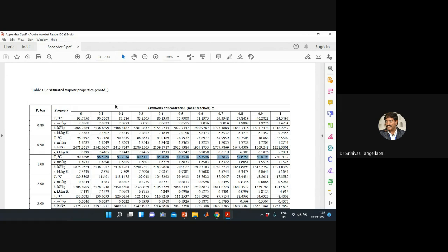Okay, now I covered the extreme ends, the fully liquid properties and the fully vapor properties. Now the question is: if the state is between these two curves, that means above the saturated liquid and below the saturated vapor, how to read the properties? First of all, before going to the table, how to conclude whether the region is liquid vapor mixture.